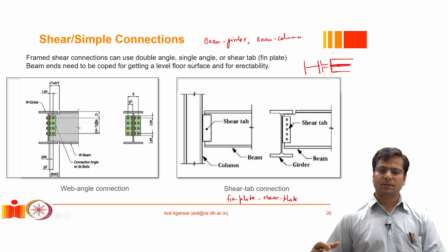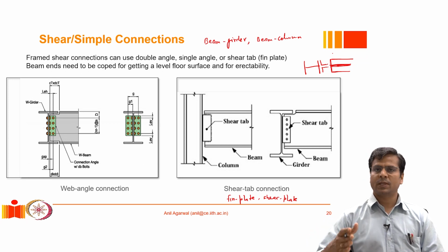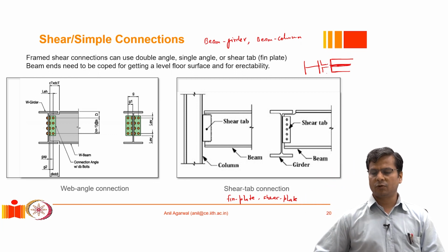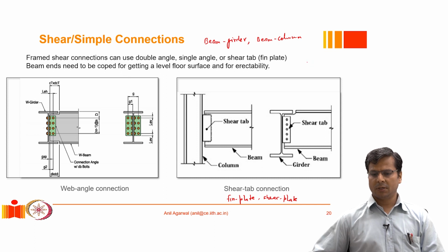But at the site, we don't have a space to pull the beam back and then slide back in. That's very difficult. Usually we have to lower the beam at the site, which makes it very difficult to place, right? In such a situation, often the bottom flange of the beam has to be coped.